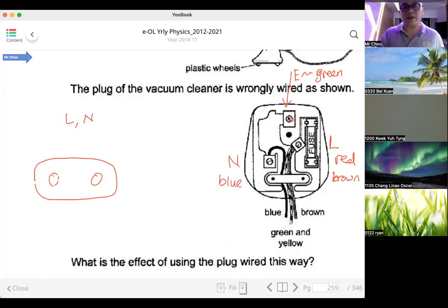Okay, same thing. This screw itself, you unscrew. You put the wire inside firmly, no stray wire. Then you screw in all the way so that the wire is in place. Okay, you do that for all 3 places. Make sure that there's no stray wire. Your wire should be all inside this hole here. There's a hole on top where you can slot in the exposed wire. Once you slot in, you screw in totally. You do that for these 3 parts. Okay, so far? Once you are done, you arrange the 3 wires properly and tuck them inside.